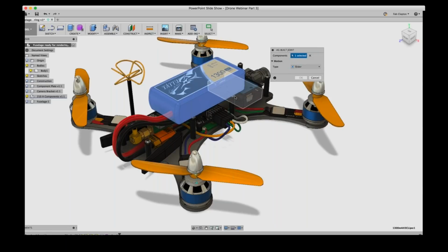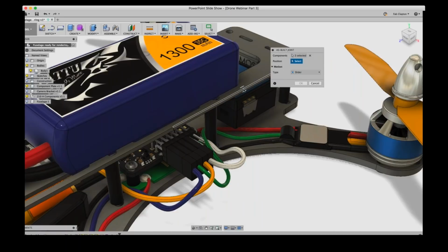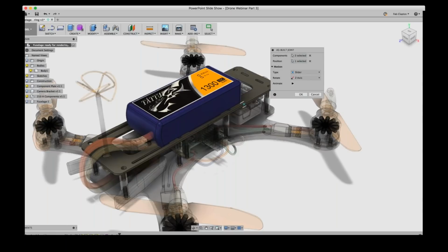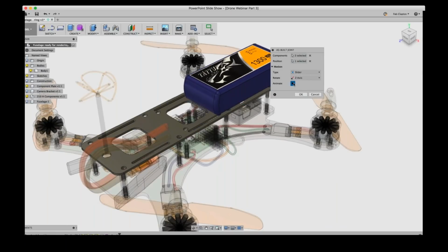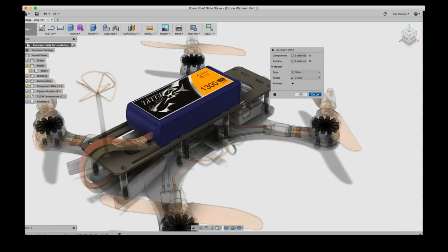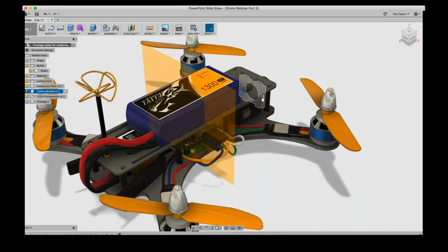And then you can select the slider, and then I have to select a reference for the slider. So I'm gonna turn that plate back on because I don't have a horizontal reference. I'm gonna select the top plate here, and then where is the reference, I select that corner there to make it slide. So you guys see how easy it is, I'm not even messing with the wires on the back or anything like that, just for demonstration. In case you design a machine, or a bicycle or something with moving parts, you can see how that's gonna go before you actually finish everything.